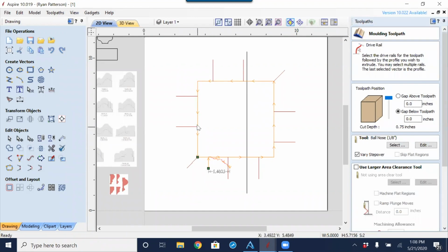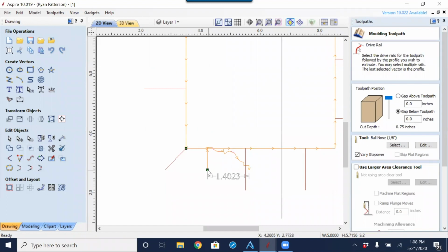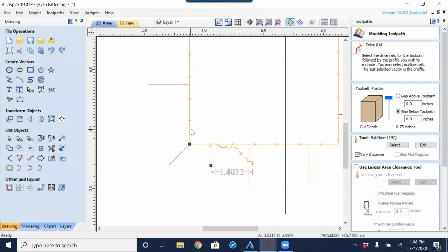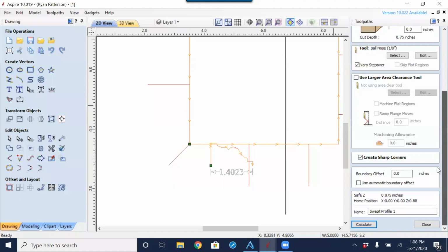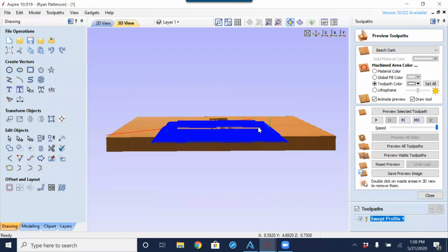And you see they are indicating which way they are going to be offset. So if I am following and understanding correctly what this start point means on this profile, this side is going to be up against here. This lower section of the profile here is going to be extended out past over here. So let's just take a quick look to see if that is the case, and it is. We can see that the higher point is here and it flows outward.